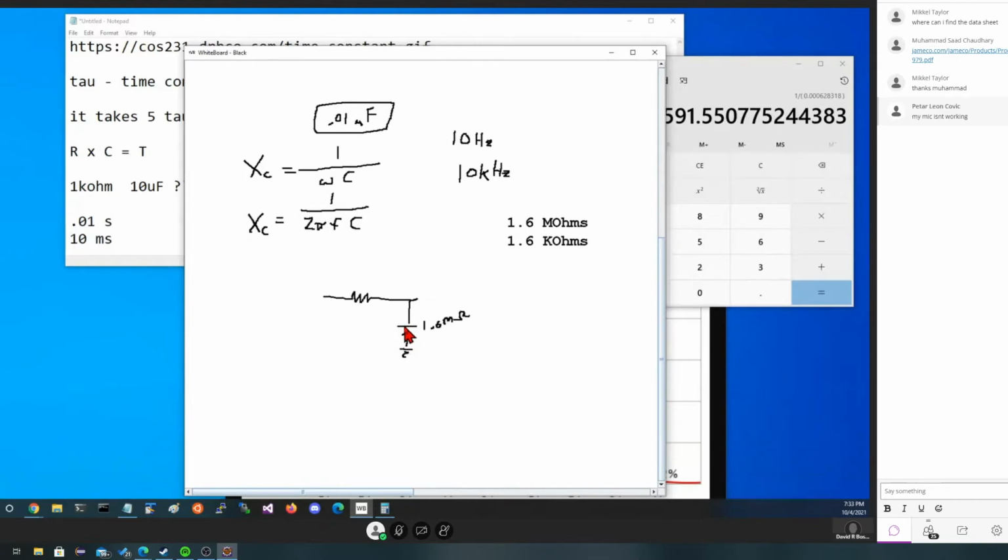So at 10, we think about this as a circuit. There's going to be some value here, which we haven't included in the circuit because it's the thing that determines where the low pass and the high pass filter. Remember the R I told you we didn't write down. But you can only imagine that as this gets bigger and bigger and bigger, more voltage is dedicated to the capacitor, meaning that the output swing here is going to be a lot higher.